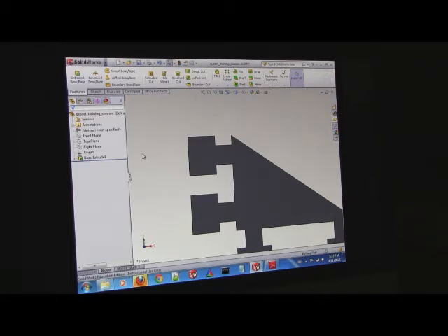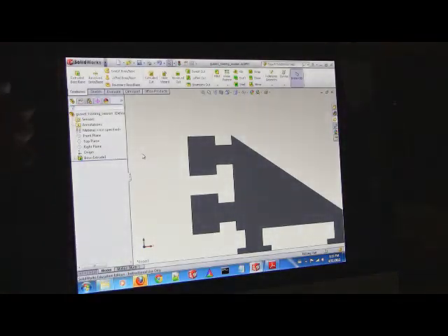There are two gussets in Lab 1. They are identical parts, except the one we're working on has two holes. So, open question. Would you start by making one part before the other, or would you just make two separate parts? If you make one part, you can save a copy, and you have the second part for free. Then all you have to do is delete one of the holes and you're done.